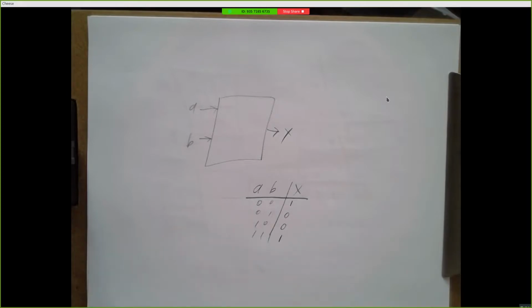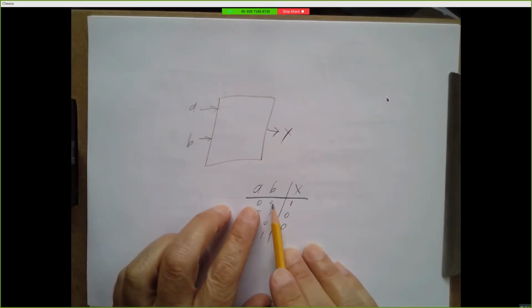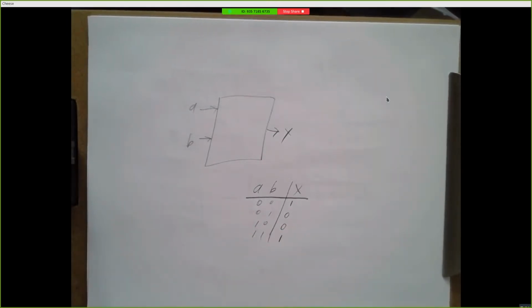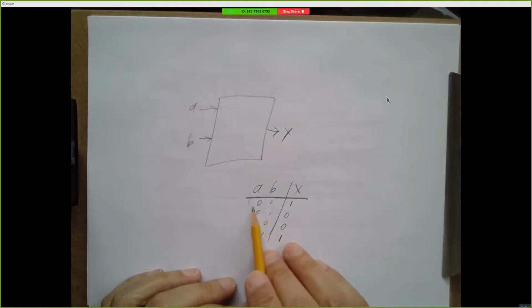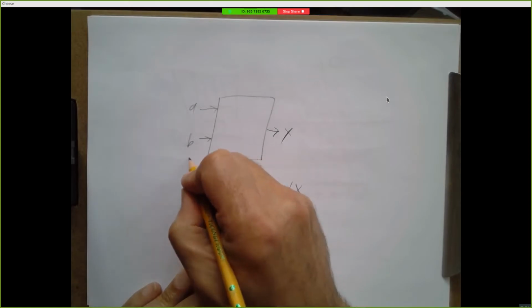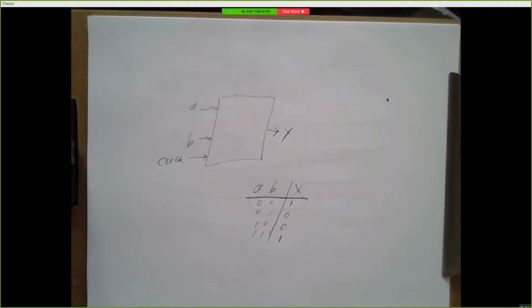But remember, when we're dealing with circuits, right, there's glitches. Values can change to intermediate values while circuitry is processing changes to inputs. There's propagation delays. And A may be on its way to becoming a 1, and B may be on its way to becoming a 0. But in that process, depending on when these things change, we might get to temporary states where A and B look the same. So what we're doing is we're making a comparator that only looks at the inputs when a clock ticks.